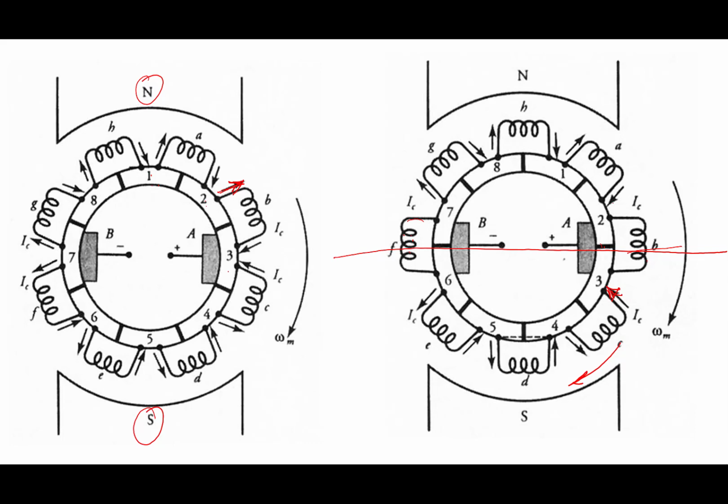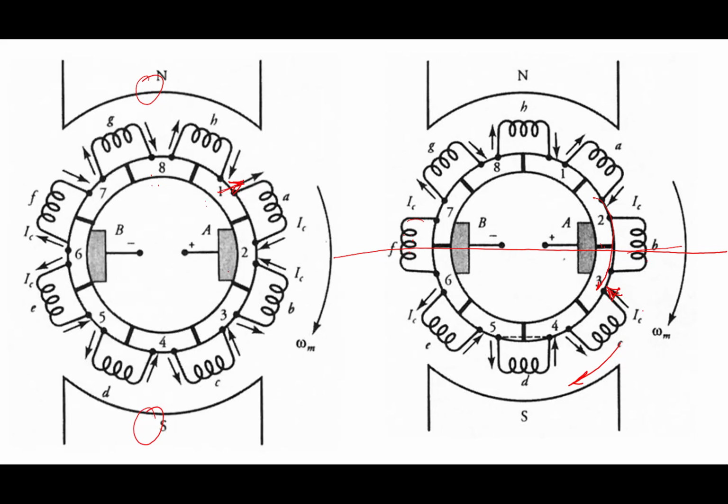So in order to change the current direction, it takes a certain time, because it is passing through this position, and here the current direction is changing. It is not instantaneous, and the inductive effect of the coil is also taken into account, right? Now when it moves further, the current direction will be in the negative direction, right? So this is the process of commutation that we saw.